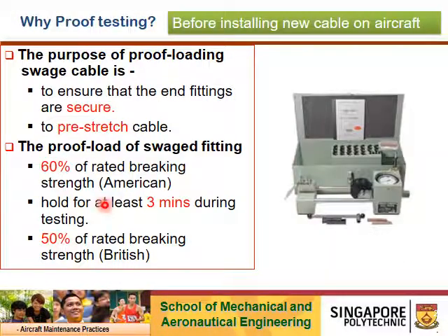So I mentioned after you manufacture or repair the end fitting, you're supposed to do a proof test. I mentioned it before in hydraulic hoses. Same thing goes for cable. We don't always change or install a new cable. It may be years, 10 years, before we overhaul and replace the cable.